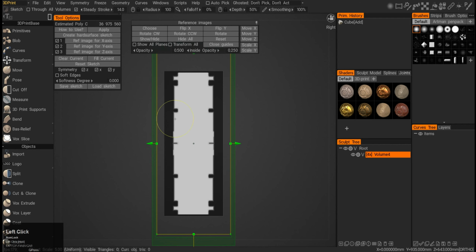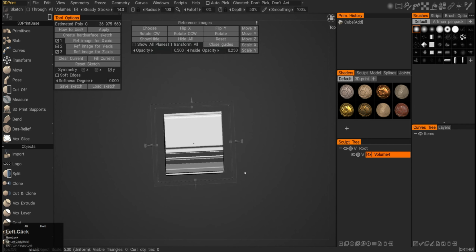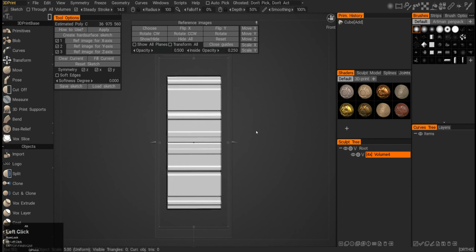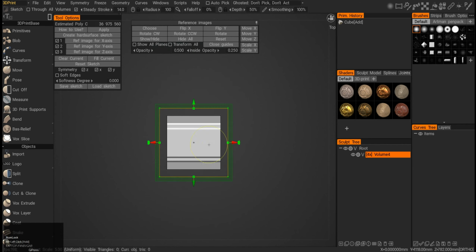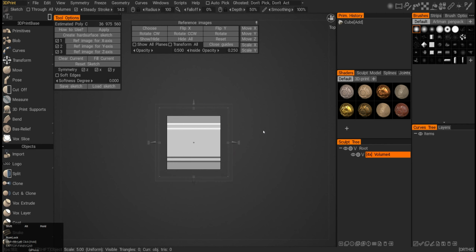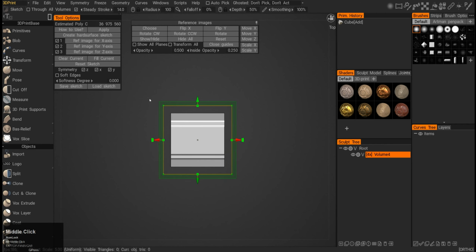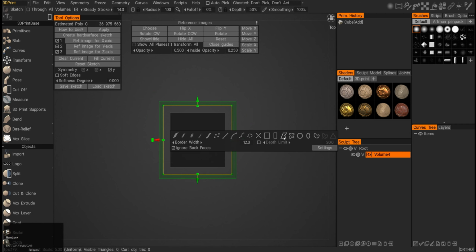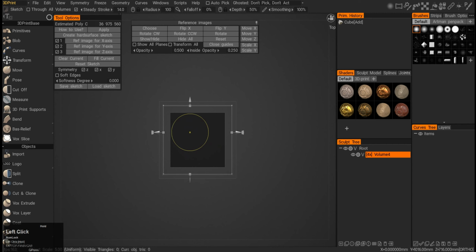Just by dragging, doing the shapes, you're already getting something like a lightsaber-ish shape from one view. If I go to the left side, you can see it's just like a brick, there's nothing there. So I go onto the top, and I'm always snapping it. To snap, I press Alt Tab. Snap the top view, clear it, and then paint a circle in the middle. You will catch this gizmo, so I just move it away, not bother with it, and just draw a circle and get it done.